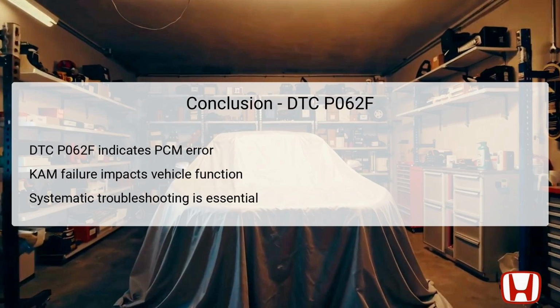In conclusion, DTC P062F signifies a keep alive memory error within the powertrain control module, potentially leading to various performance issues in Honda CRV models from 2011 to 2016.